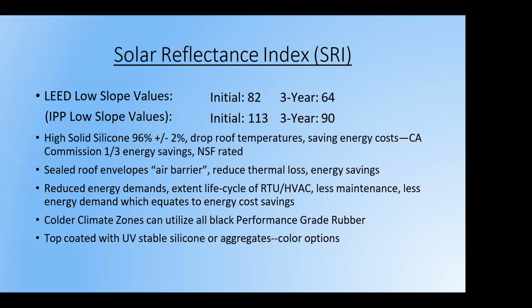So there's no roof products rated under Energy Star anymore, but you can look at CRRC and pull up the products through their page. If you're looking at LEED or LEED Silver, there's minimal SRI requirements. You can reach out to the manufacturer, whoever you're dealing with, request their third-party ratings, and make sure they meet the standards that you have, whether it's executive order, FAR, or LEED program. Next slide.